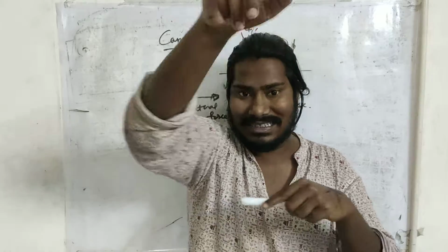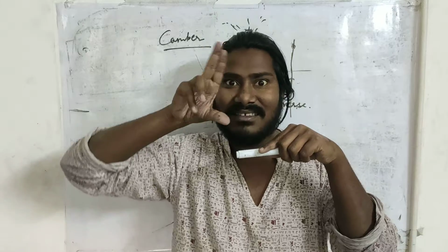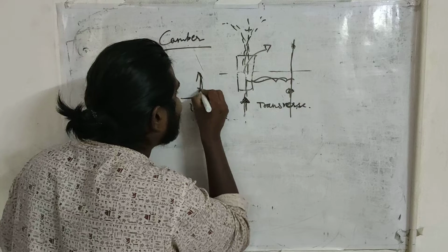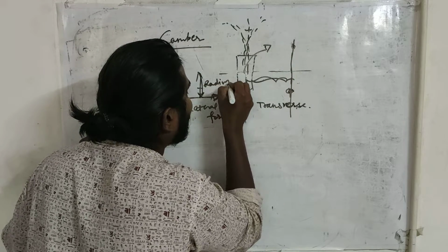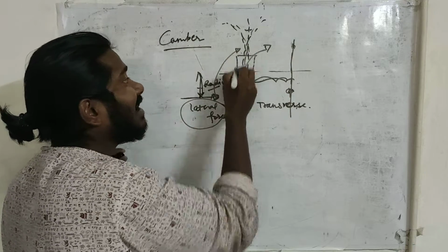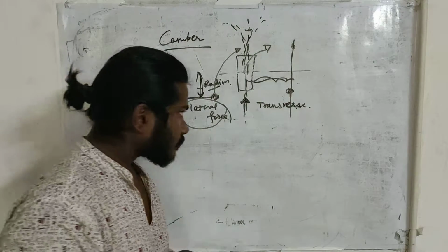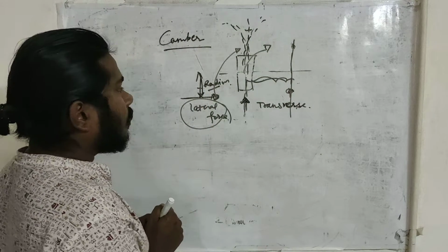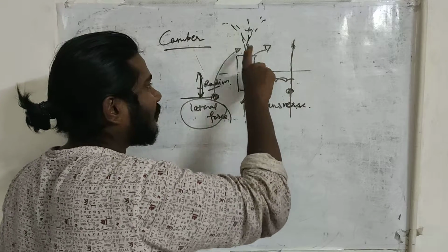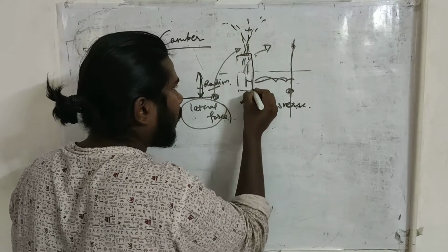Only if I am having the trail. Whenever this is happening and your tire is having this camber change, your tire is going to have a camber change because of the radius of tire. So whenever you corner your vehicle, this will also try to create the camber change in your vehicle. So now, how is it going to provide the camber change? If the resultant of whatever forces are acting, this is the static position. Now, this is the static loading.